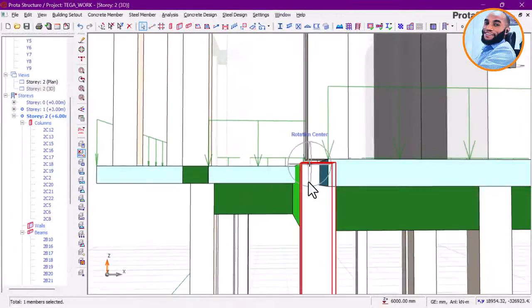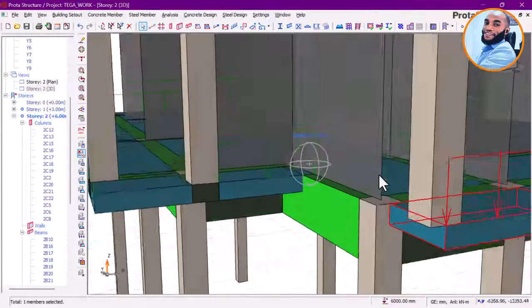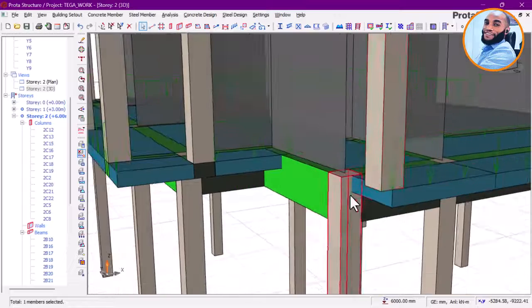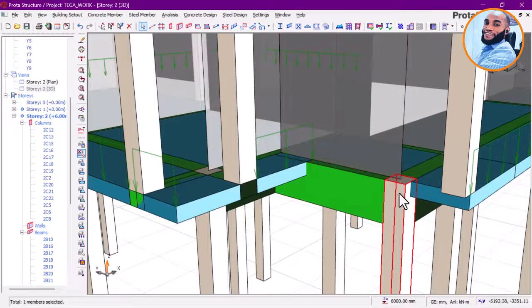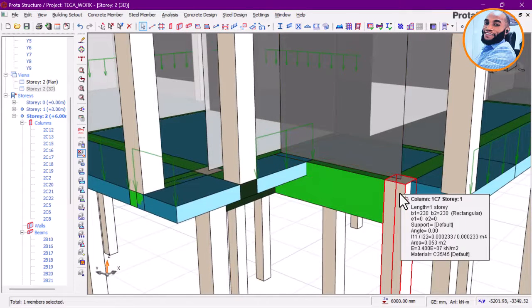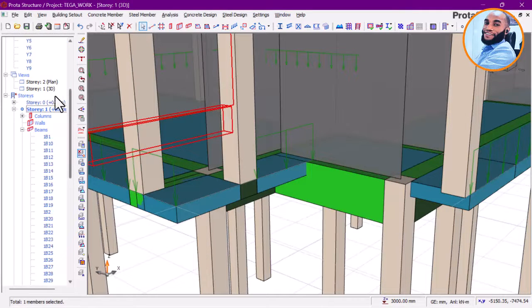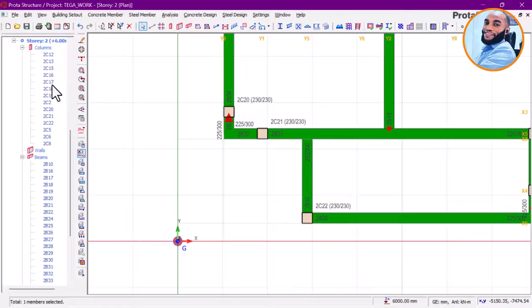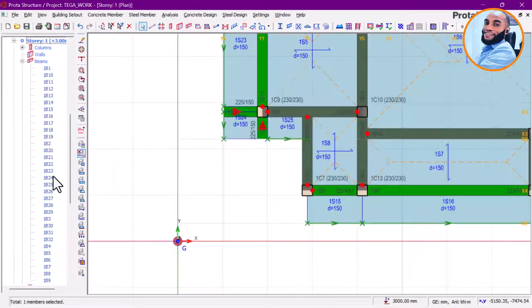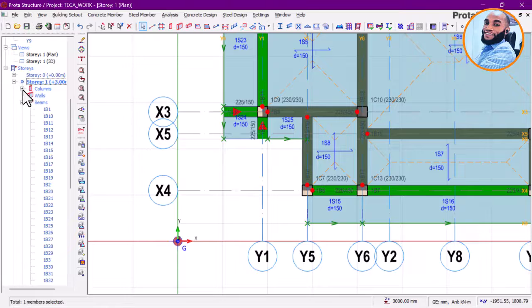Okay, there is no cantilever beam here. Can you see that? Oh, that's bad. So let me see what's happening here. This is column what? Column C7. So I'll go to my plan view, make sure I find column C7, and put a cantilever beam there. Locate my column C7 on my grid line again. Column C7, this here, correct.